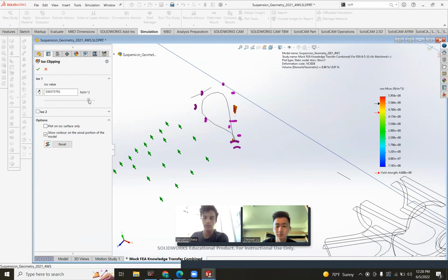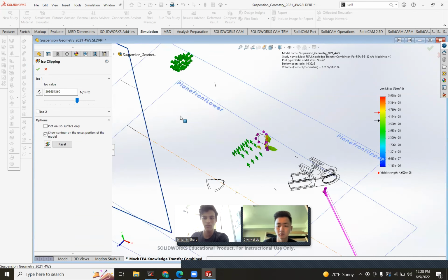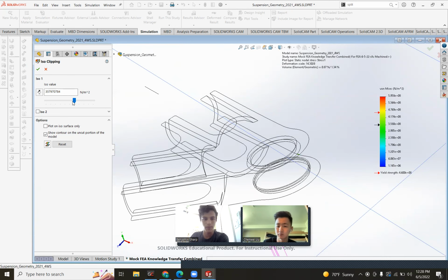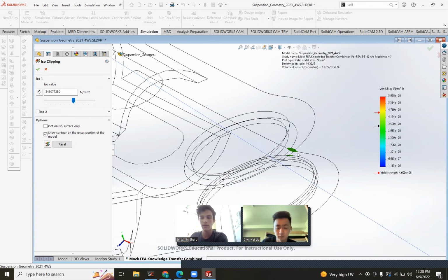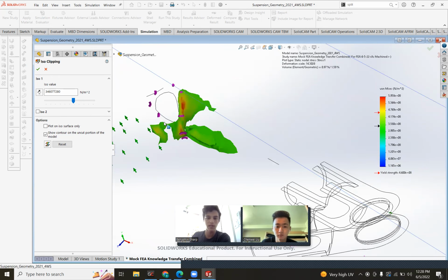So this failure here, though it looks bad in the FEA, it's probably not real. It's probably just bad FEA. But then this one in the bearing cup is almost definitely real and worth noting because the mesh is so fine, and this is actually how the part appears in real life, where this is different.